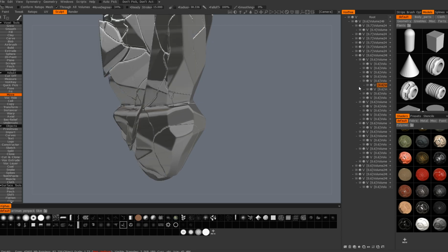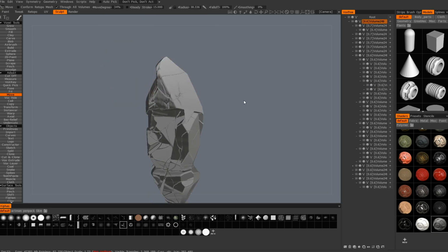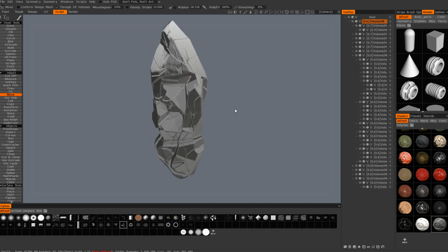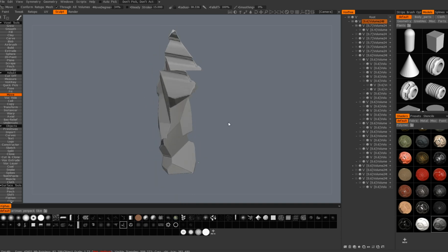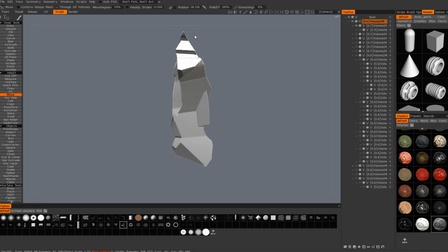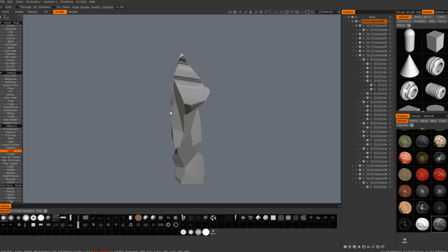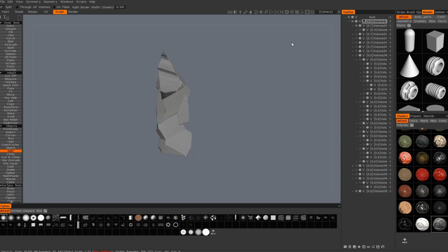But before I say that, what I want to do is deal with the root volume layer that's kind of visible every time. If I try to isolate any of the cuts, it will still be there, the main original big shape. So I want to split it out and create an empty root layer, just like a group layer. And now I can hide it and have this guy here. Otherwise I cannot just isolate one piece. It shows me the root piece as well, the volume 249.